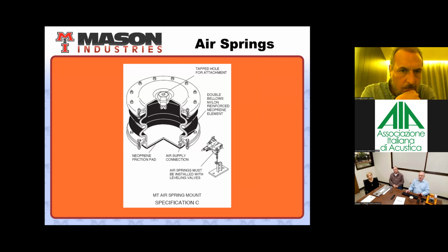We get into situations, another weakness with the efficiency equation, is that when you get into very high frequency systems, the springs often don't work, although the theoretical efficiency will tell you they're going to be very effective. Air springs are effectively a rubber bladder, capped top and bottom, pressurized to support the load. And the beauty of air springs is there's no steel contact between the equipment and the structure. So you eliminate that sound transmission path. Very often used in retrofits where you've had a vibration problem.